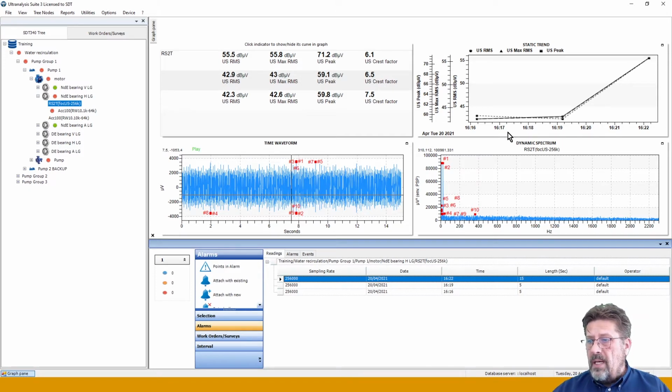There can be a difference between a 5 seconds measurement time and a 25 seconds measurement time. So you sometimes want to exclude this point from your graph. There is obviously a reason why we took it. As I said, during taking measurements I can say there are some changes in the process and I want a longer measurement to see how my machine behaves with the change of load. Fine, you can do it and you should do it.